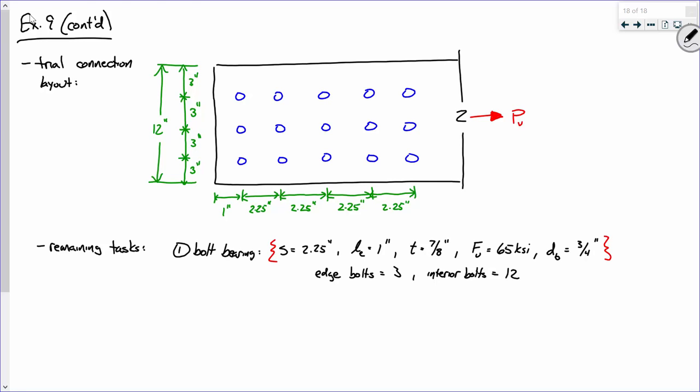So when we were looking at tension members, we didn't care about that. But we're not looking at this as if it's a big tension member. We're looking at the physical capacity of the connection. My point is, for bolt bearing, we're looking at the physical dimensions in the hole. When we look at gross section yielding, net section fracture, and all that, we're asking what's the strength of the member as a whole. Does that kind of answer your question?